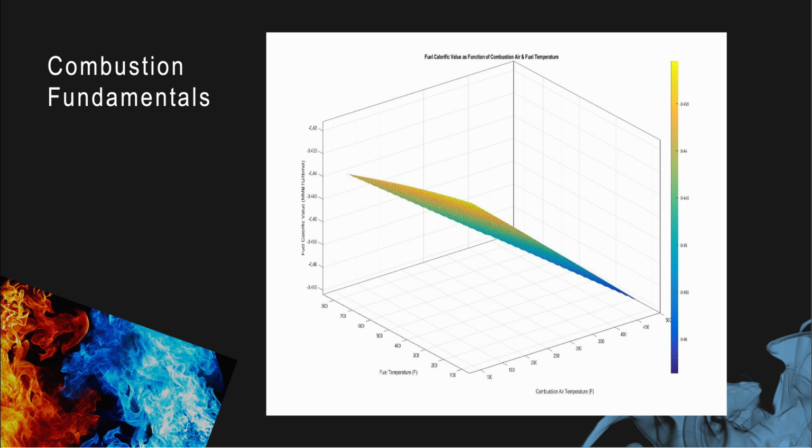And the reason is that when you look at the air versus fuel mass ratio, the combustion air is super significant by mass. So it makes perfect sense to preheat the combustion air versus the fuel. Because at the end of the day, if you only preheat the fuel and it's a small amount, it gets mixed with the air. So this is the ABC of anybody looking at improving any type of fuel system: let's preheat the combustion air.